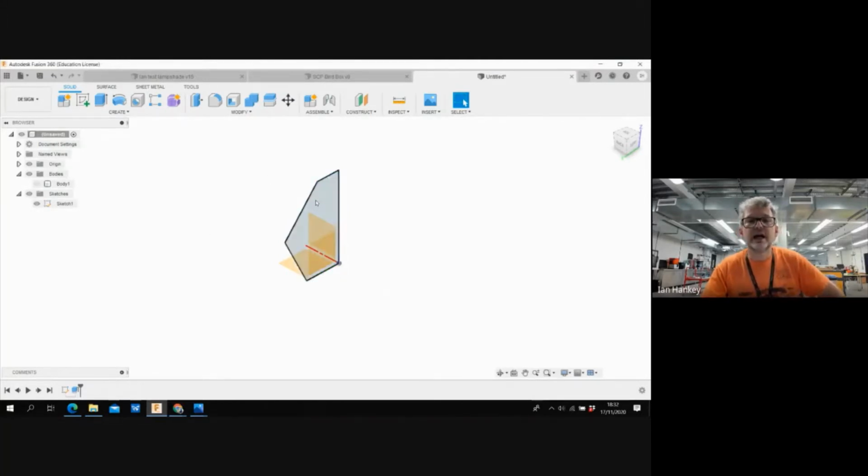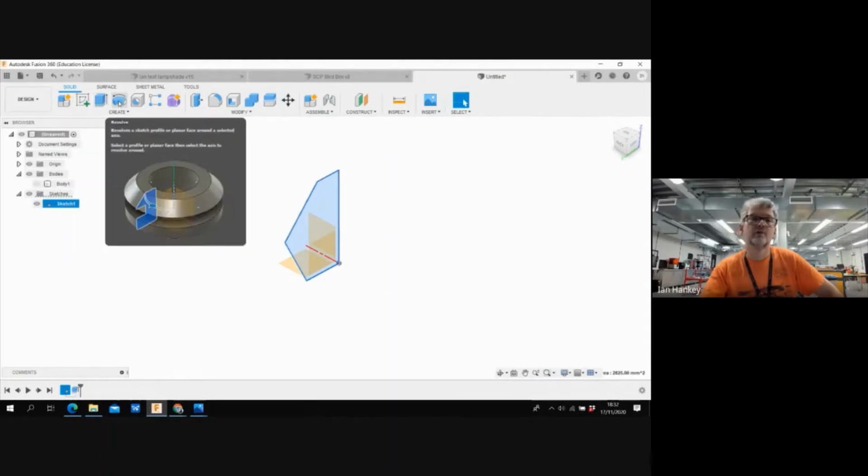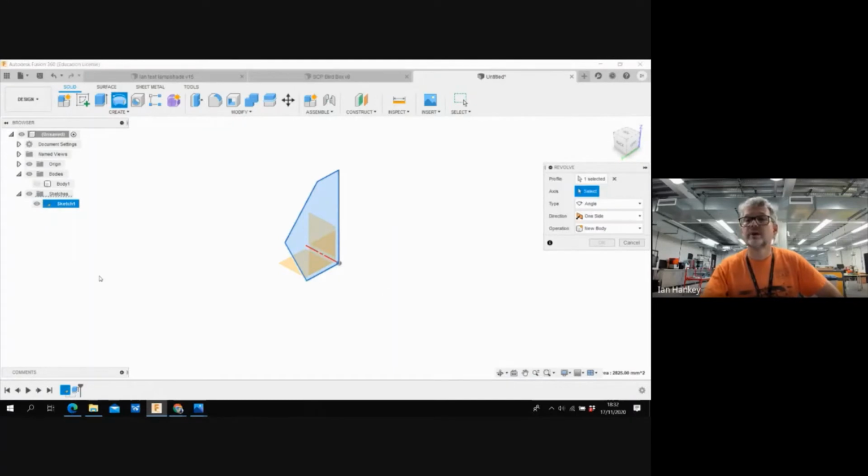So what I'm going to do is highlight that sketch, the plane inside the sketch, I should say, and then go to not sketch or extrude, which we just used, the next one along, which is revolve. I'm going to left click on that, and we get this box appeared. So the profile is already selected, which is that one. I'm going to reselect it actually. The axis now it's asking us for is actually the blue one here.